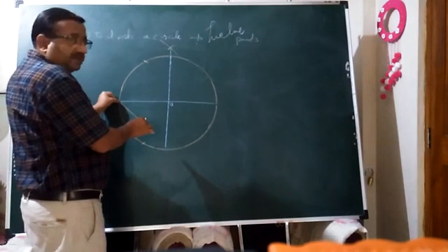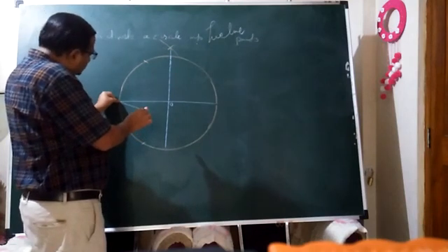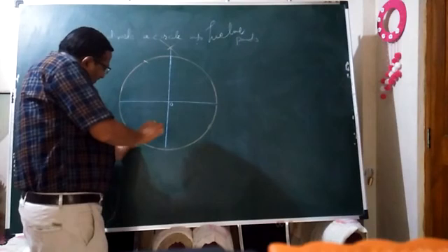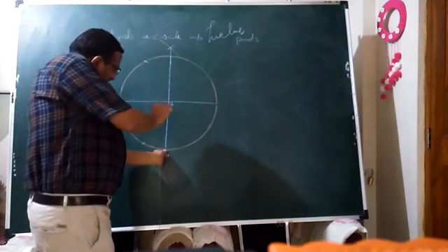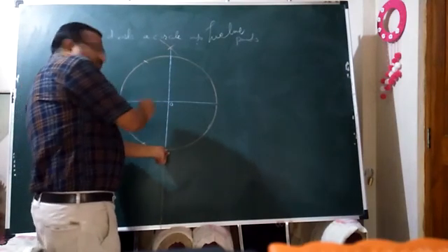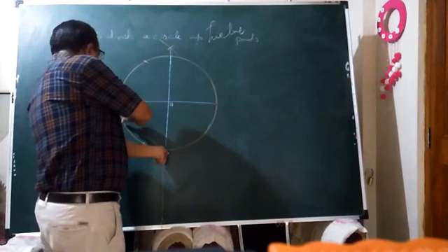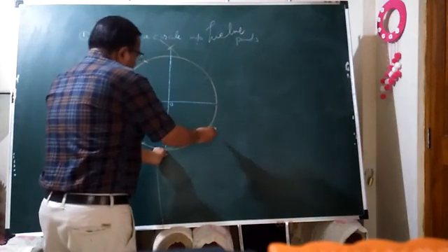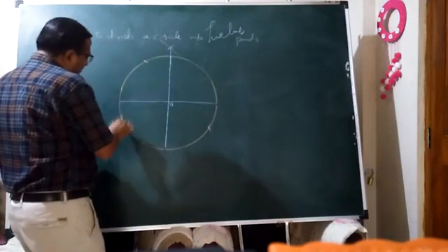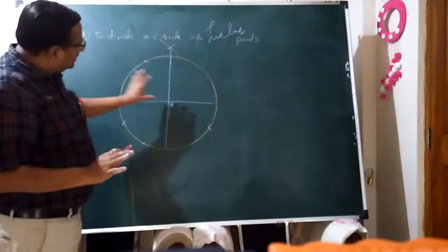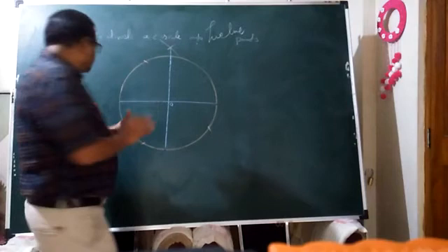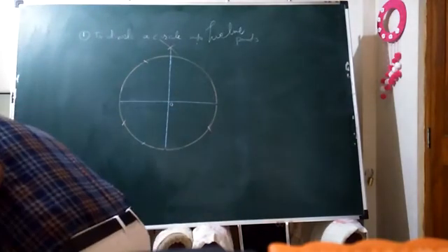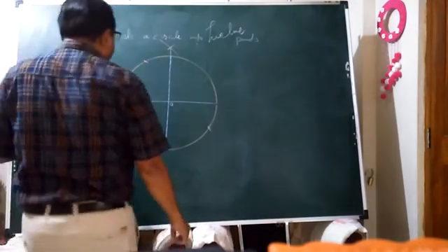What next? Through 90 degrees, just change the position of the needle, get it here, and get another 2 arcs of the same radius, the circle radius, in this way. First, second, third, and fourth. Only these arcs are sufficient for getting the 12 divisions of this circle.